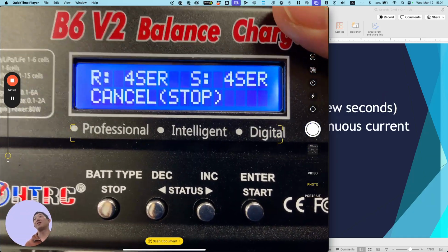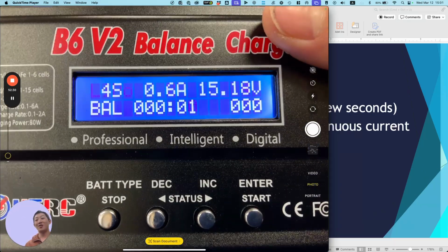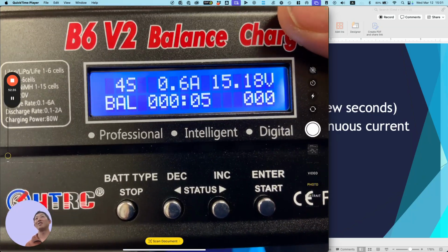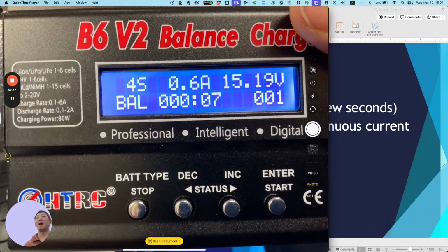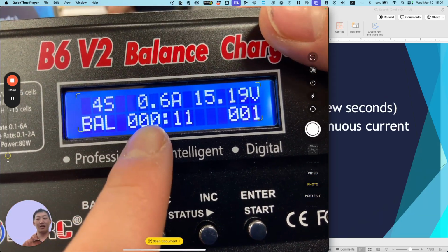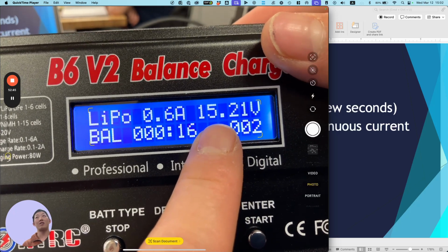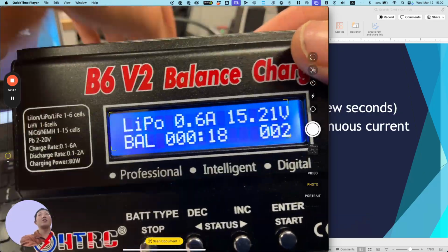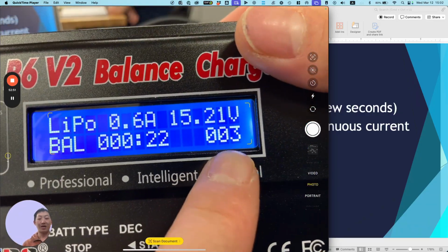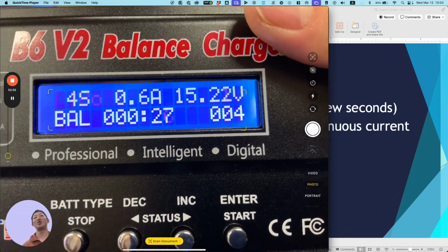And it works now. So that error message was not exactly the most descriptive of the issue. You just have to be aware balance charging requires you to plug in the balance leads. If you look here, we have some stats. The top right corner tells us our current voltage across the cells. We just read that on the meter, so that matches up. This bottom right tells us how many milliamp hours we are basically restoring back.